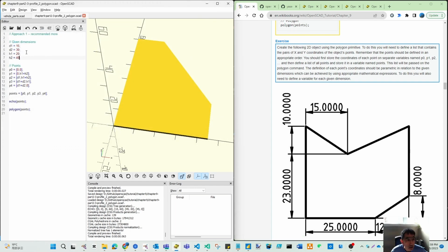Okay, how many D? So let's remove this. For D, it is 1, 2, 3. So I should have D1. D1 is 25. D2 is 12. And then I see whether I have the D3. Is this 15? Do I need to build this D4? D4, because it's not defined here, but it should be the D4. Should be D1 plus D2 minus D3. So let's define that anyway.